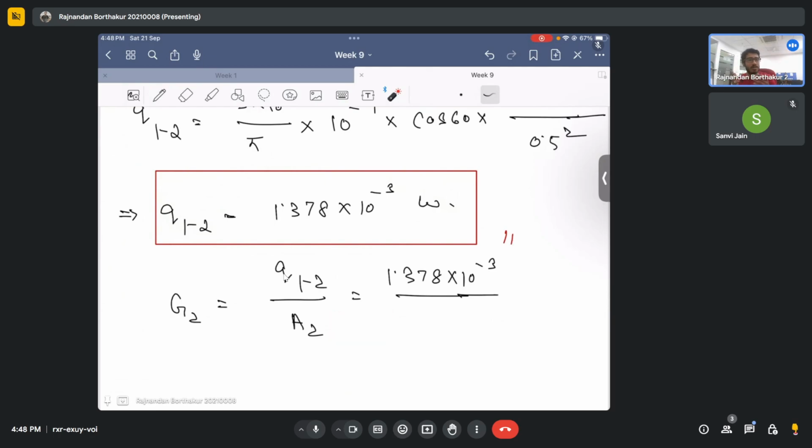It is simply because when we calculate the radiant energy leaving a surface, we calculate it with respect to the projected area, and that's why the cos theta term came into the picture. Similarly, when we calculate the solid angle, it's the angle subtended by the area in the direction normal to the direction of the emitting radiation, and that's why cos theta again comes into the formula of the solid angle. But when you are calculating irradiation, it's just how much radiant energy is falling on a surface per unit area of that surface. And that's why it becomes A2 and not A2 cos theta.